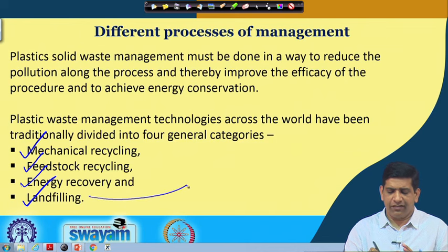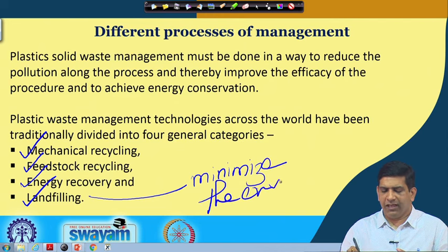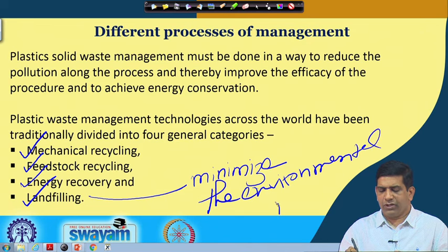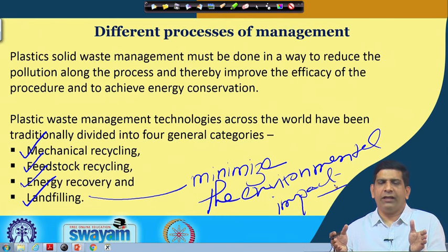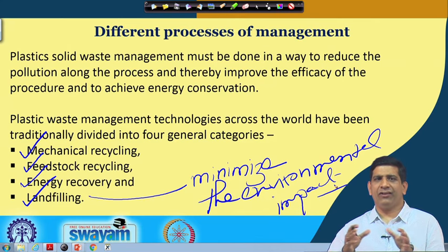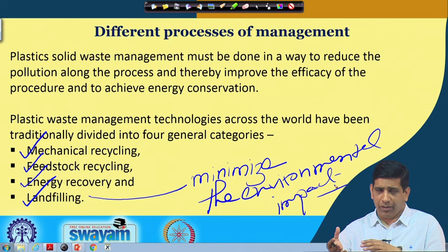Landfilling is essentially done to minimize the environmental impact, because an engineered landfill is a waste containment system. It is a waste containment system where you can keep the waste and try to manage it, and whatever leachate is produced, you treat it, and you collect the gas. So you are trying to control the impact coming out from the waste. It's not so much a treatment system as a containment system from an environmental protection point of view.